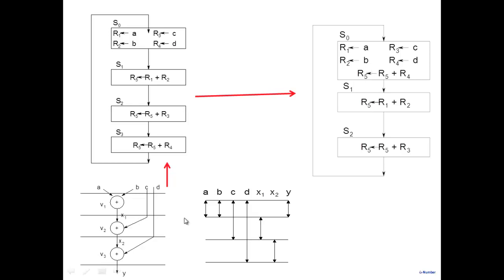So remember that when this diagram is drawn, implicitly it has been assumed that yes, there is a cycle where I would load, and the last one that you see here will be folded back into the load. So this diagram is for this kind of ASM chart description, not for this one. This is an intermediate step that you can add and quickly take this particular part, fold it here, and arrive at this. Then there is no inconsistency. But if you look between here and here and drawing Y here, then there is a problem. Y is not required here. Y is required in the upper cycle here, okay?